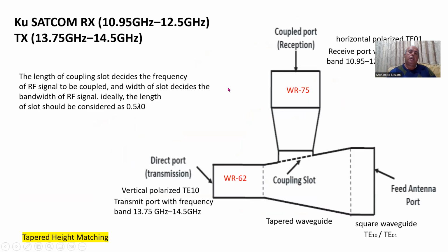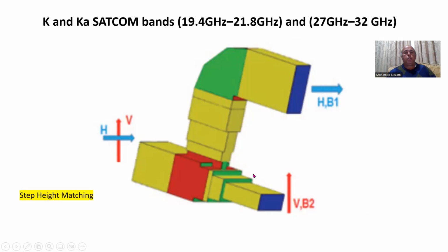Okay, so now this one is with staircasing, with step impedance matching, and usually the length of these is a quarter wavelength. So this is really nothing but a multi-section quarter-wavelength impedance matching, okay? Sometimes you might see some kind of iris in here to cancel out some of the susceptances associated with the opening in here, okay?